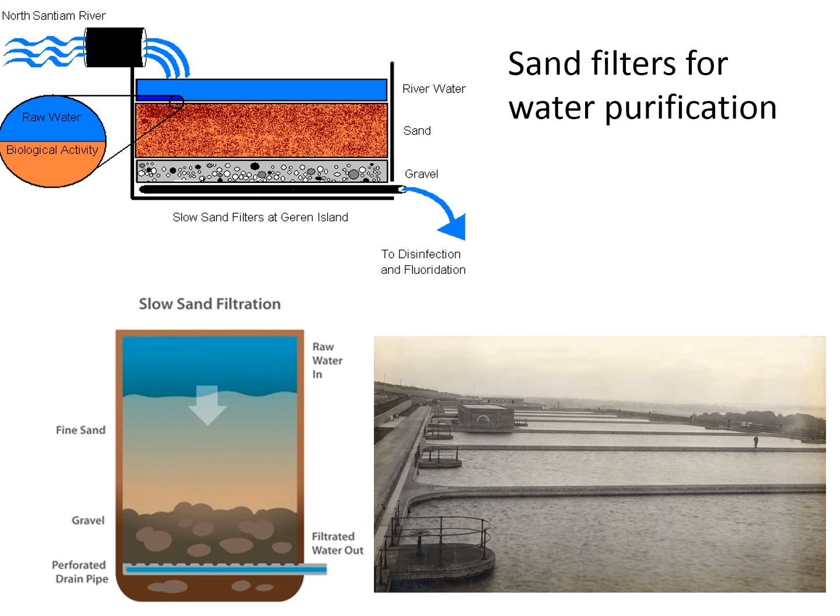So here this is the figure of typical sand filters. Generally the water which is coming will be passed first through the sand layer. Generally fine sand is provided at the top layer, then medium size range, then after that gravel, and through the under drainage system it will be transferred to the next unit. This is the aerial view of a few filter beds, and there are two types of filtration generally used, that is slow sand filtration and rapid sand filtration, and you will learn that in detail as a unit.